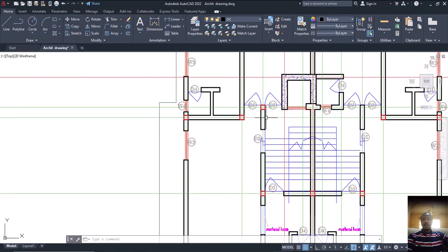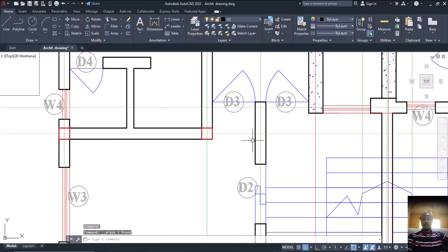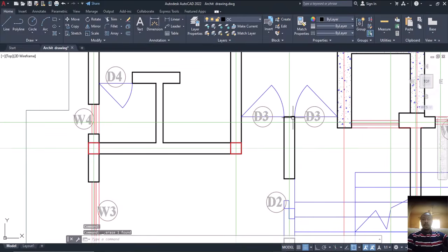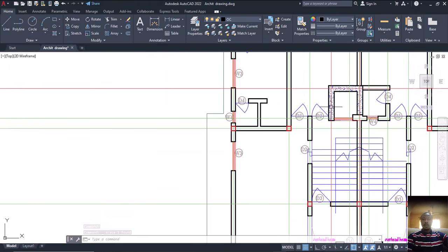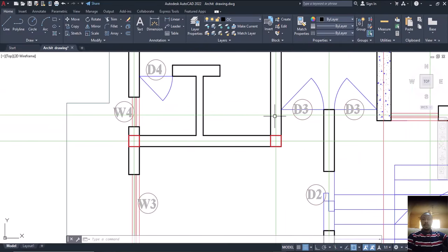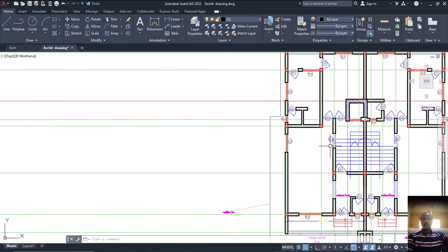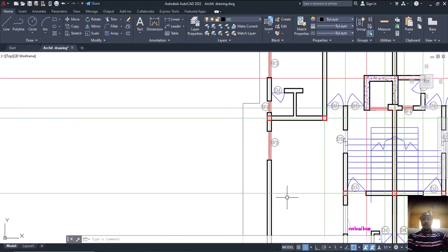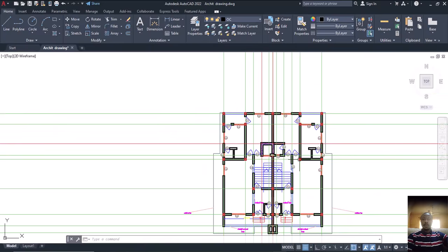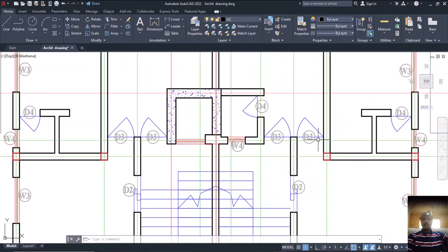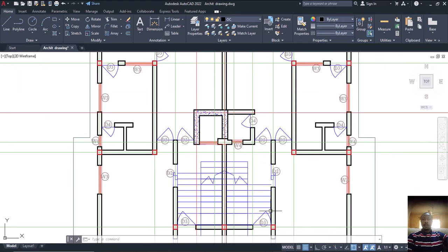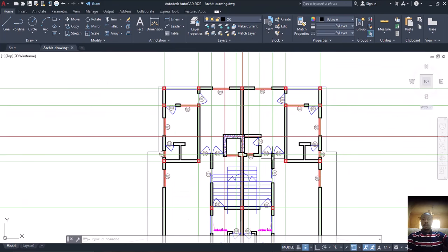Now for me to now have this beam, let me delete this one. Let me delete this. So I can now have a secondary beam. Definitely this one, I must have put a wall. Am I correct? I must have put my wall like this here, isn't it? So definitely my beam will run from here to this place. If my beam is running from here as secondary beam to this place, automatically this one will now come and rest on it, which makes this place close, isn't it? So I now have this place more as a slab, and the same thing applies to this place now. If I now have my secondary beam run like this to this place also, isn't it? And this one will also come to do what? To rest on it, isn't it? So that is that.